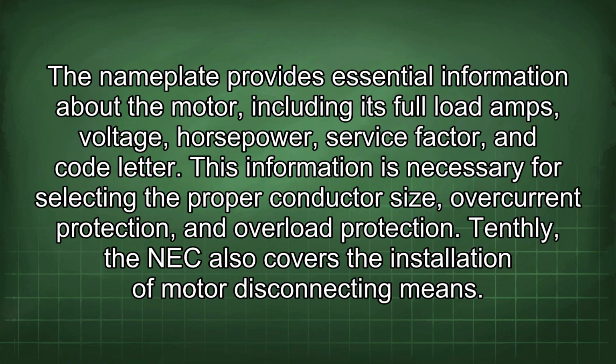The nameplate provides essential information about the motor, including its full load amps, voltage, horsepower, service factor, and code letter. This information is necessary for selecting the proper conductor size, overcurrent protection, and overload protection.